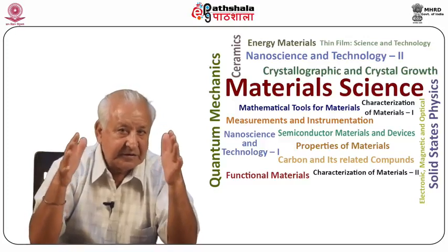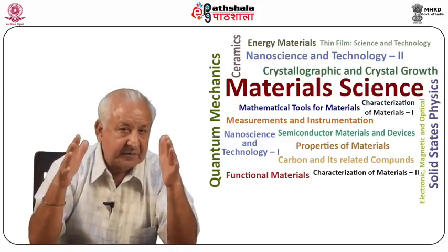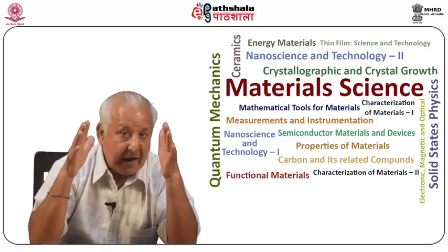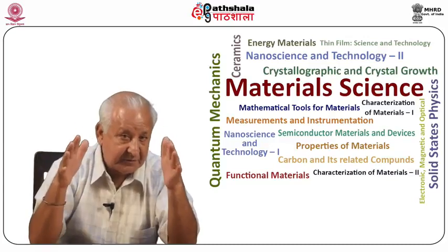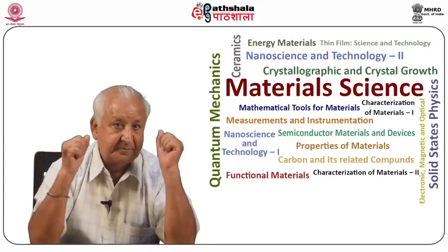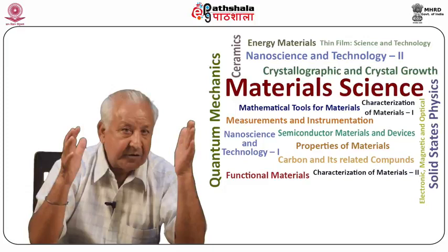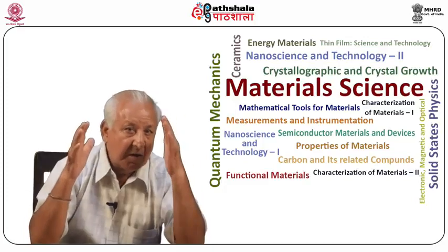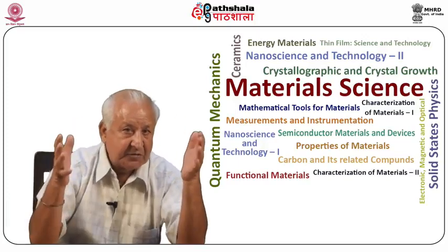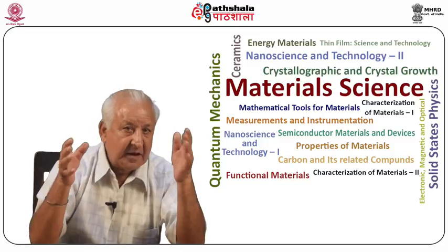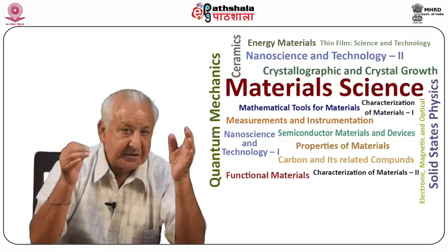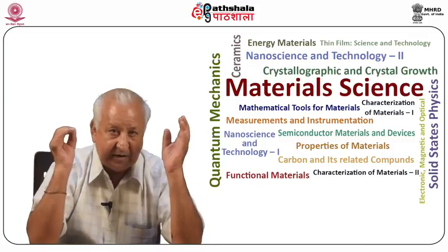The growth then proceeds as usual, see figure 30.7c, but the crystal is covered by a layer of encapsulant which prevents it from decomposition. The crucible and RF coils are placed in a pressure vessel. The pressure is required to be more than the sum of the maximum partial pressures of volatile components. However, this pressure should also not exceed a particular limit. Heat transfer by convection increases with pressure, and at high pressures, the rate of transfer is time dependent.